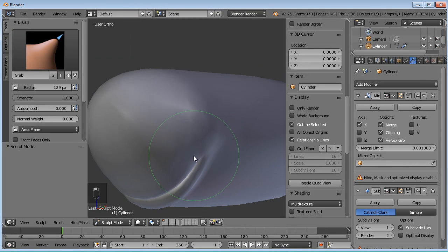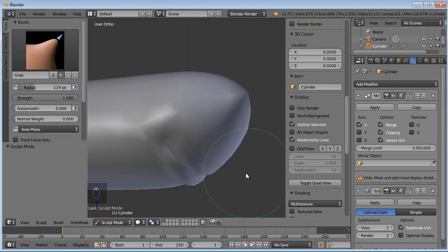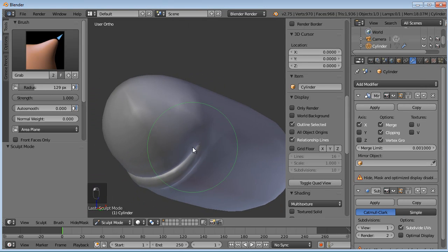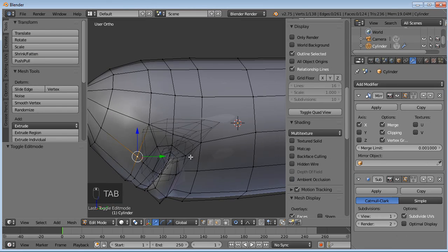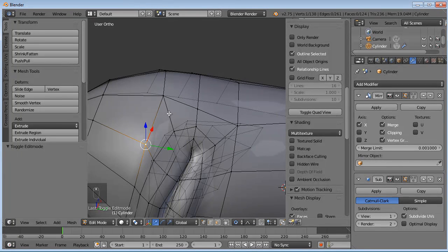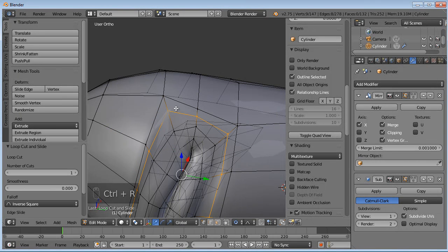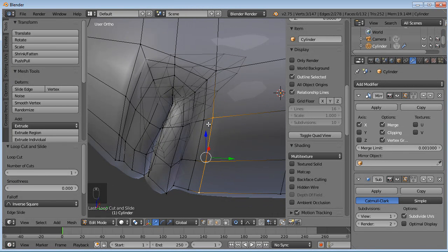Make it look organic. Even though it's going to be a steel plated surface, we want it to have that organic look, so it's kind of the Pixar living car. So get that a little bit more. Give him some poofy cheeks. Might need to add a little bit more underlying geometry for that, so let's tab into edit mode. Let's add one more loop right here. So let's add that in, and then maybe we can grab this one so there's not such a close proximity.